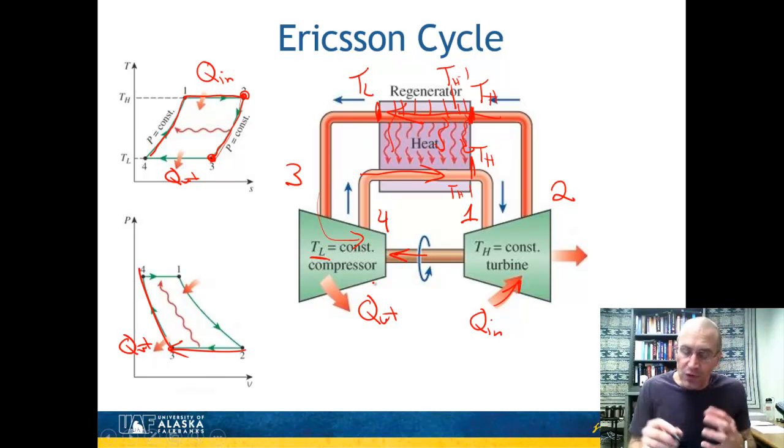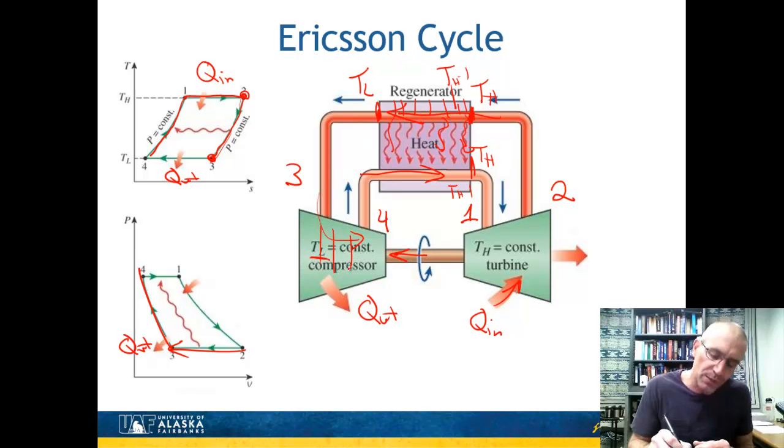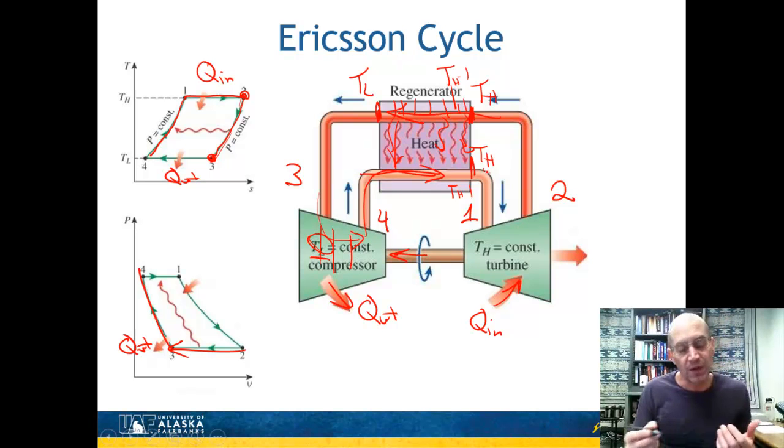And I do have to do it. It's difficult to engineer because I've got to have it designed such that as I compress it, each time it goes through a particular stage of the compressor, I remove just enough heat to keep TL constant. Then I'm going to go through the countercurrent heat exchanger. There's the regenerator just dumping heat through into this fluid to come out at TH. There's an Ericsson cycle. It's only interacting with 2 temperature reservoirs, one at TH, one at TL. If it's internally reversible, meaning no friction, therefore it would be completely reversible and would have the same efficiency as the Carnot cycle.